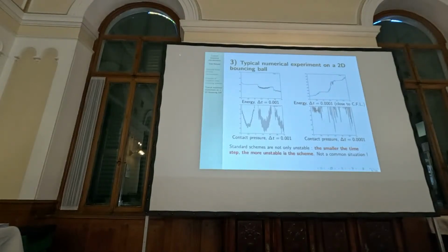And when the time step is decreasing, the thing gets worse and worse. In fact, with the smaller time step, things become unstable, and the contact pressure is such that we cannot do anything with this. So it is very specific to dynamic contact problems that as you decrease the time step, it becomes more and more unstable.